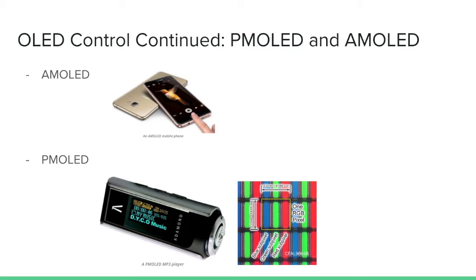And these problems are negligible at small screen sizes. The amount of voltage needed to drive each light is based on the total number of lines. A rough estimate for the maximum allowed screen size would be 200 times 200 pixels. At this point in time, the main reason to use PMOLED would be its low cost due to an easy production.